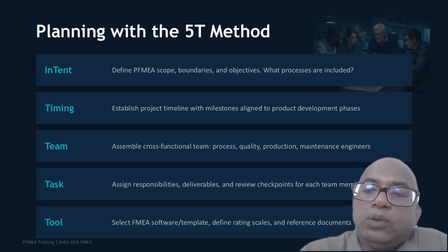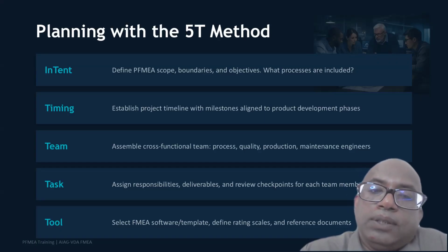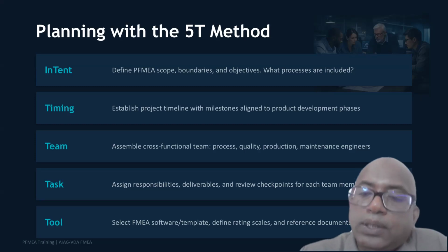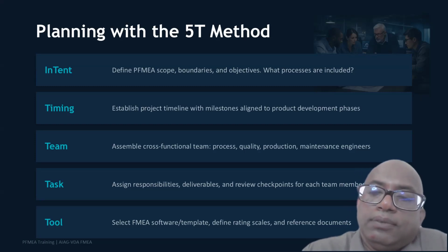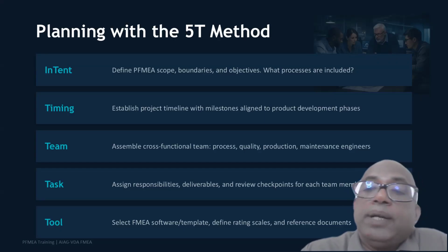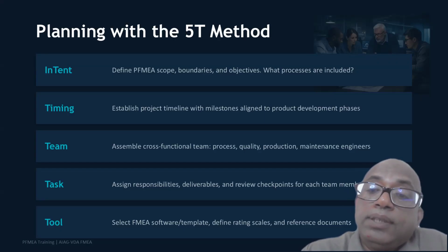And team: assemble a cross-functional team. Everywhere I am talking about the cross-functional team, CFT. This is a very important part in your PFMEA preparation process. Process, quality, production, maintenance engineers, and everybody. You have to collectively prepare this PFMEA. Otherwise, the quality department or quality manager alone cannot prepare the PFMEA, right? This is a teamwork effort that everyone should understand, right?